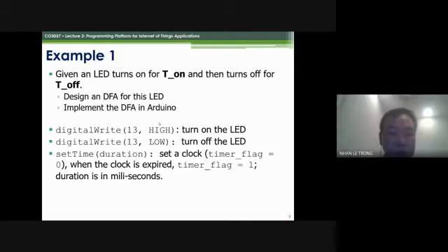We do have some firmware instructions. Like I said, when you need to turn on an LED, you need an instruction, and it is the firmware instruction of the system. Here you use digitalWrite. The main function we're going to use to turn the LED on and off is digitalWrite, and I just need this one to design this program.